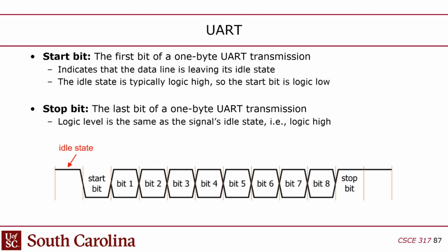And then the start bit has to be asserted for 1 bit time. And there's no clock, so what's a bit time? It's whatever the internal clock says it is, right? And then you just send the bits over serially, and then you give the stop bit. And that's essentially the format. Usually it's 8 bits, but you can have 7 bits or 9 bits. That's configurable. But either way, you have to agree on that ahead of time. If there's not an agreement, you'll get corrupted data.